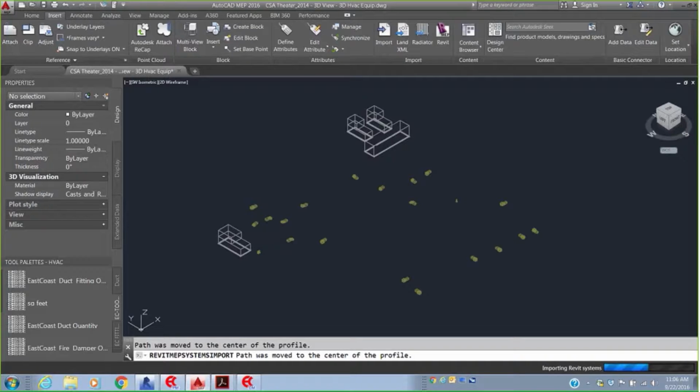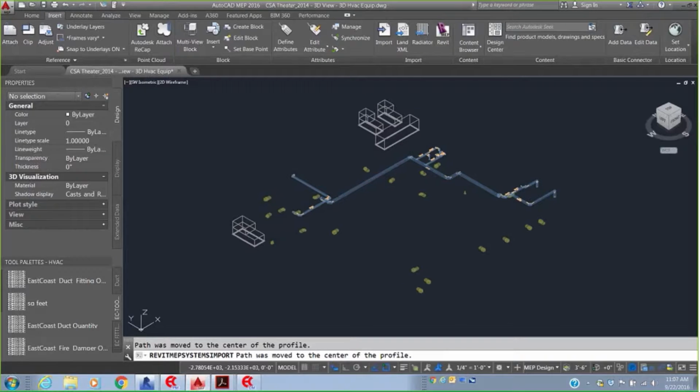They had no specification in Revit. They knew the shape, and they knew the location, and they knew what the object was. But there were no gauges, no locks, no connectors. In just a few seconds, you're going to see that exhaust system painted up on my screen. And it will have all the information as far as the specifications and everything that we've assigned to it. So there it's painted up onto my screen now and brought in that Revit model.